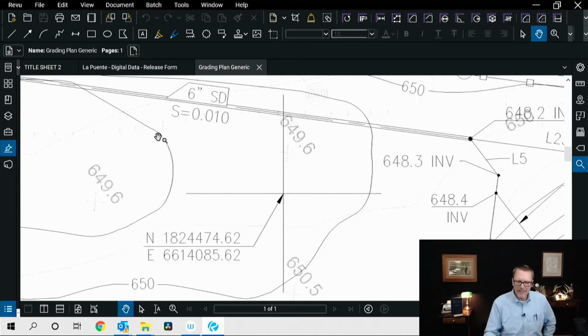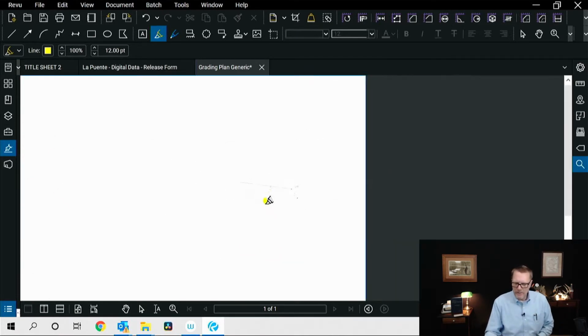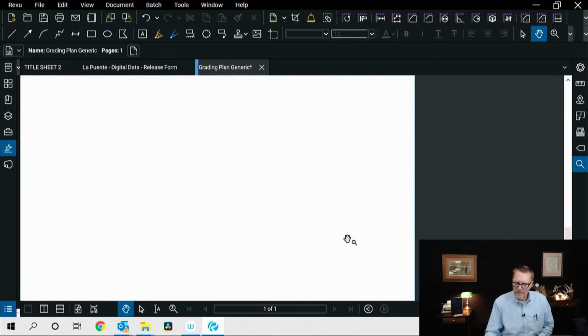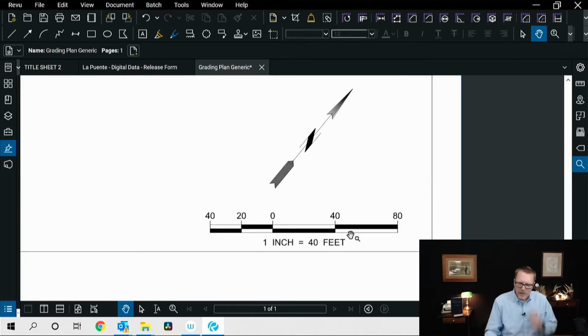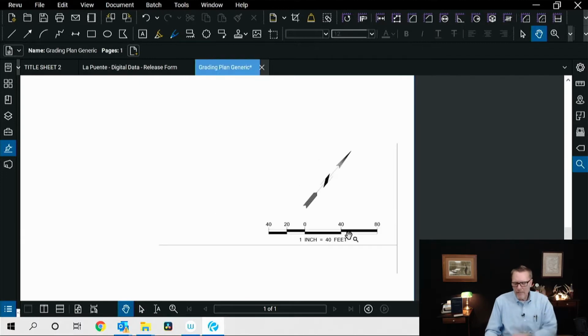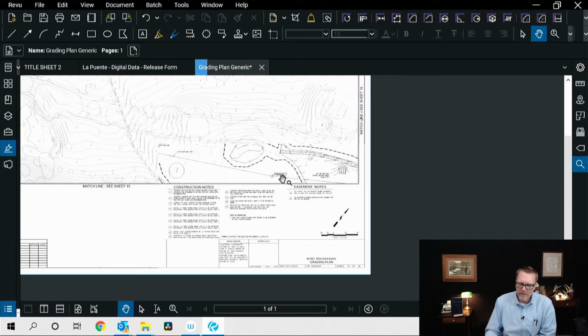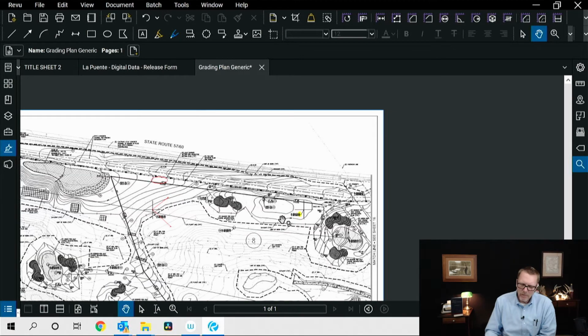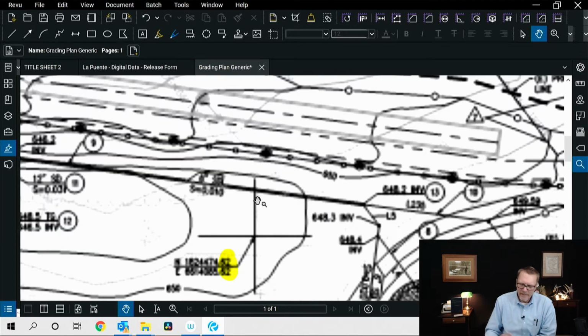How do I know it's nonsense? Well, first of all, I see here that it shows hundredths. Grid ticks, if you look at this particular plan set, it's a 40 scale, so your grid ticks would be good within about a half a foot at a 40 scale. And so when you look at it, what the process was, and this is another thing I can tell you